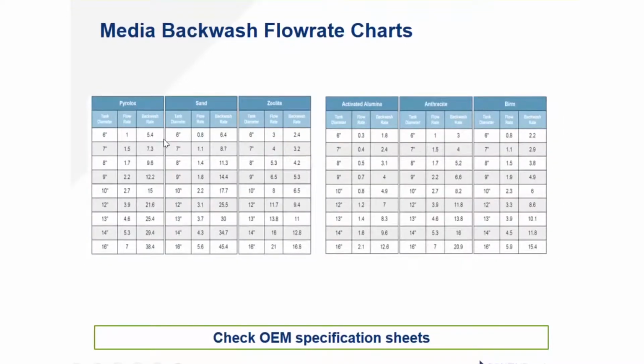Most water softeners and valves on the market, water softening media is very light compared to all these other medias. Very, very easy to adjust for softening media. Now, when you're dealing with heavier medias, you're really going to have to pay attention to your flow rates and your pressures involved as well to get these medias to lift.